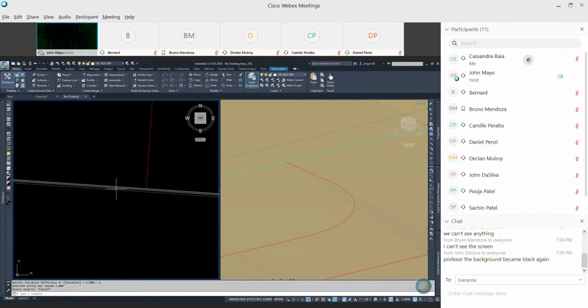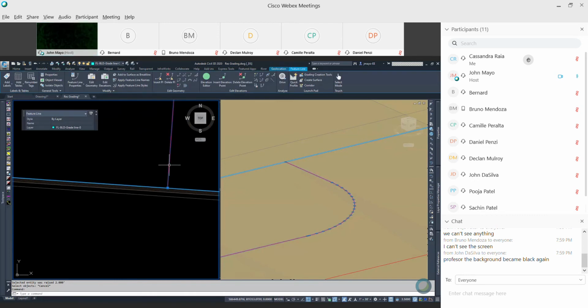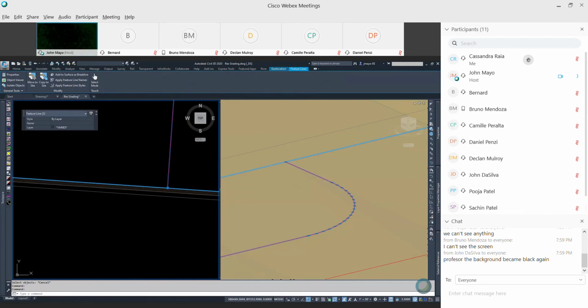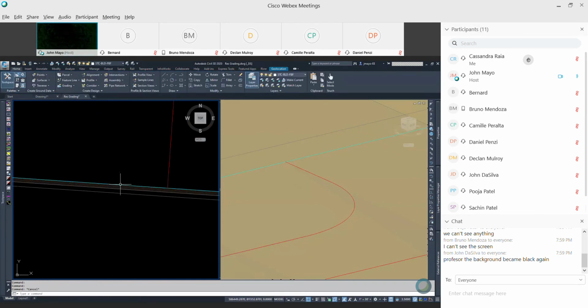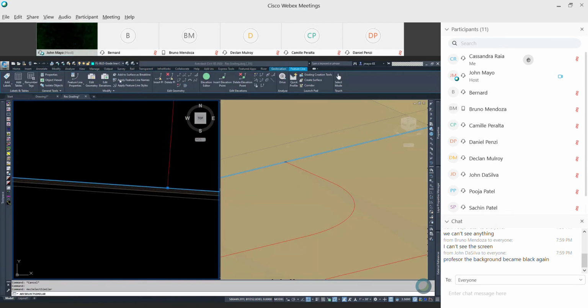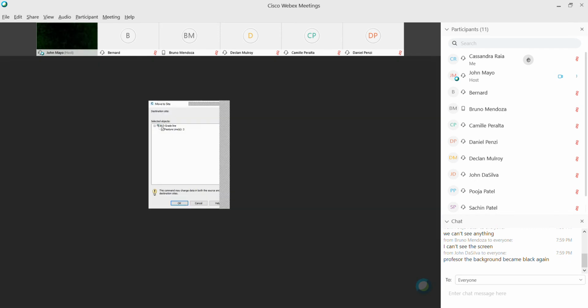So if I take all of these and all of these, I can't do them together. I need to do them separate. So take all of my grade line feature lines and now move them to a common site.